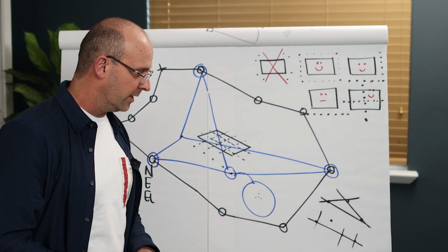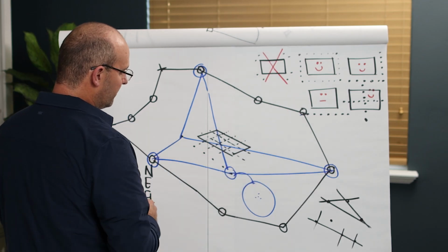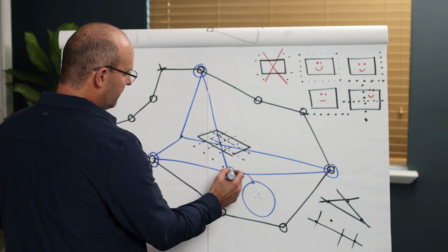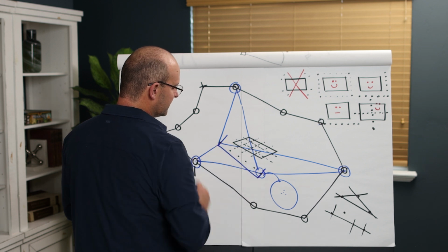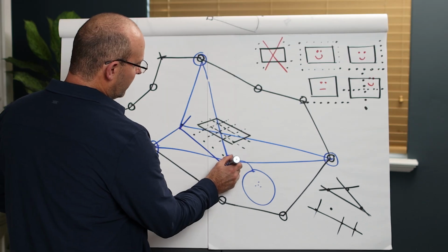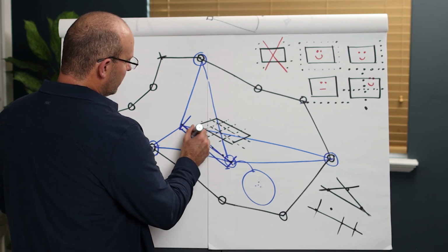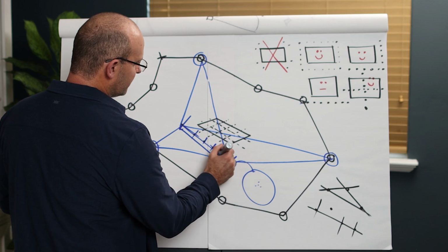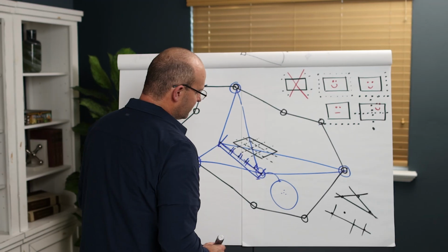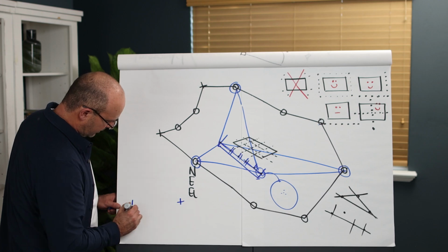Now, here's the key point. When I'm setting up my secondary, I don't want to lay these out from my primary. I'll just go from here to here, and then I'll verify a couple things. That my distance between the points is accurate. What I'll do is I'll mark a line forward, mark a line back, and I will then shoot a distance forward on these, and then set up over here and shoot a distance on these back. So let me actually bring that out a little bit more clear. Let's say I have a point here and a point here.